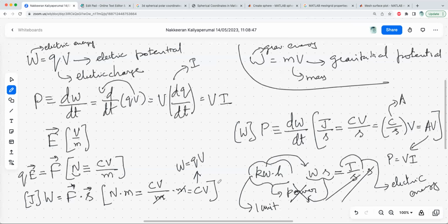Then we need to pay at a rate per 1 unit, whatever they charge in rupees. That amount is the exchange we are giving for the electrical energy, not for the power. Do you get that? Rather, let's say there are 10 different appliances at home, and they are all 1,000 watts. That means 1/10 of an hour is enough to consume 1 unit. Makes sense to you?